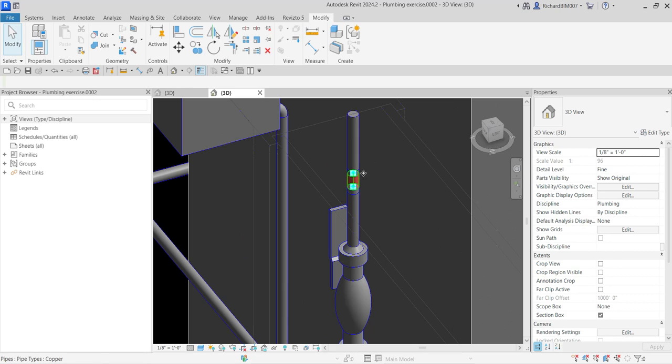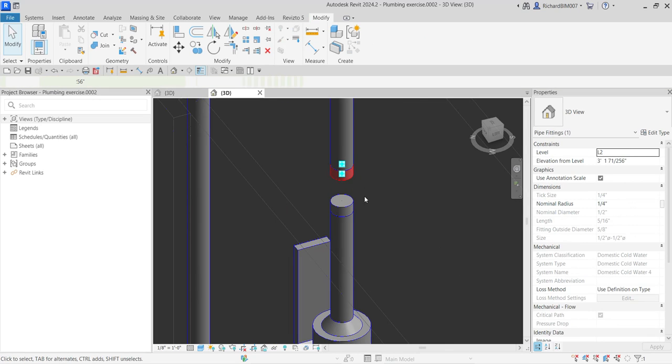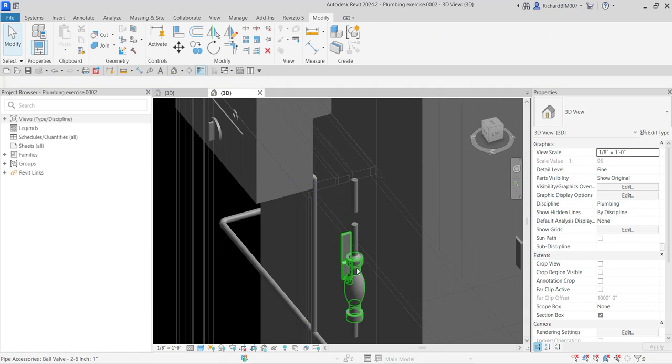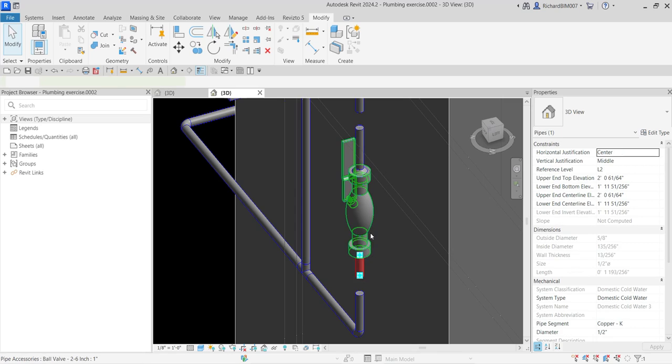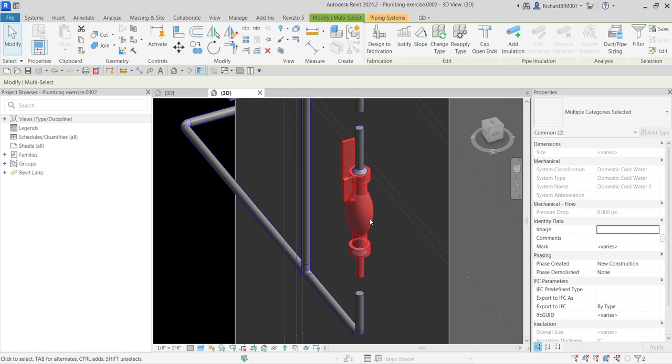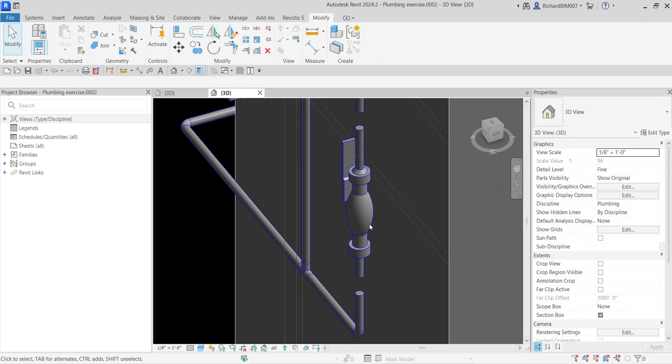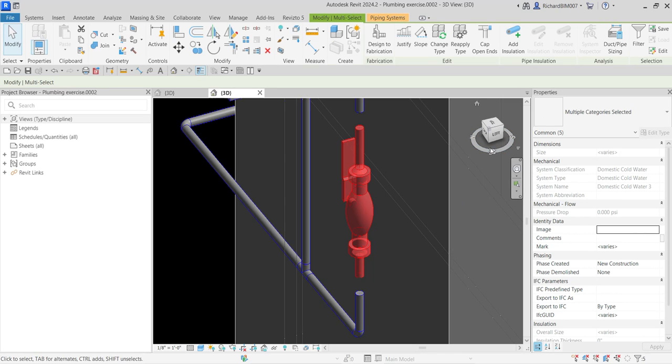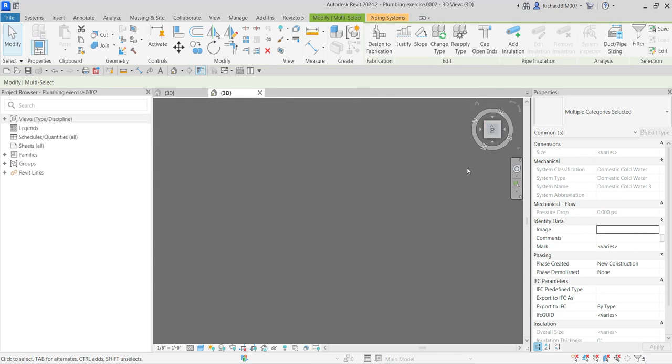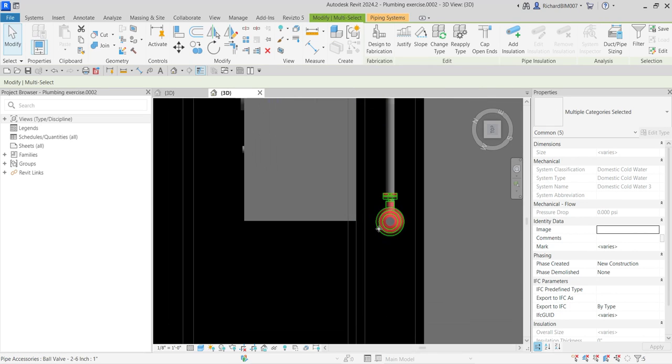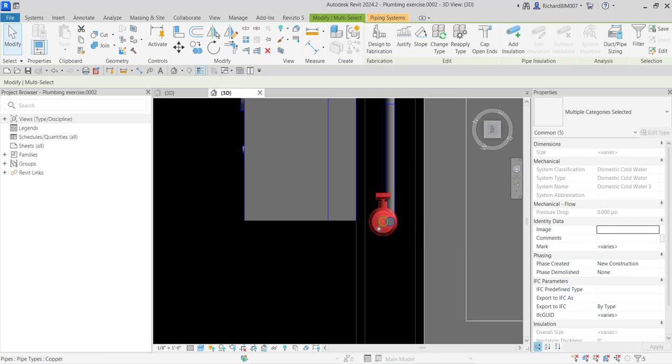All right, so delete that fitting, and then let's select this pipe here, ball valve, and then maybe let's hover our pointer to the ball valve and then press tab, and then it will highlight the network of connection, and then click, and then let's go to the top view, and then let's use the keyboard left. Let's put it outside. Okay, like that.